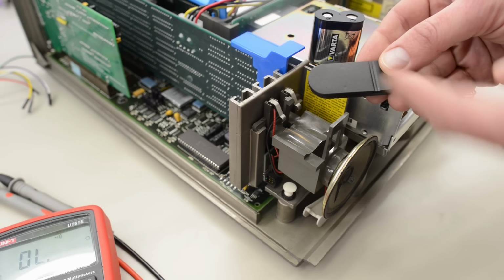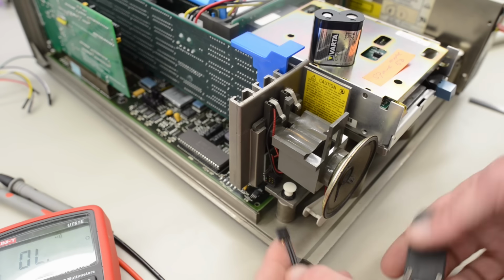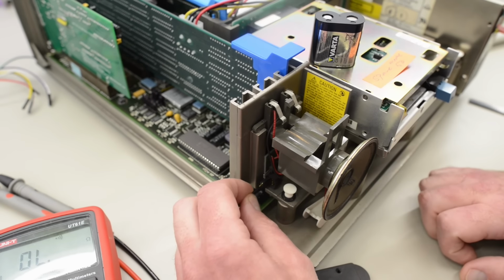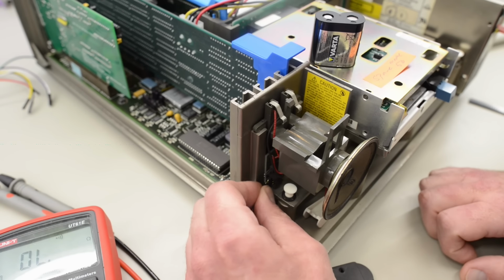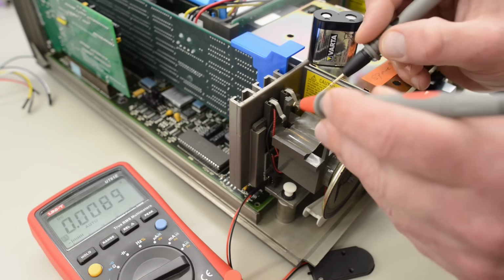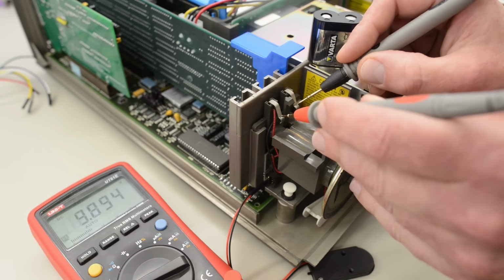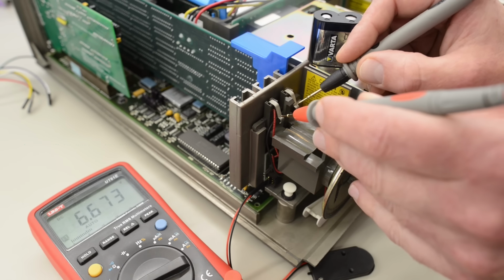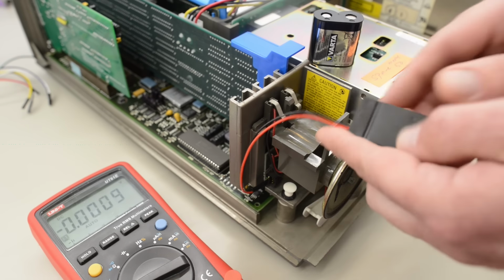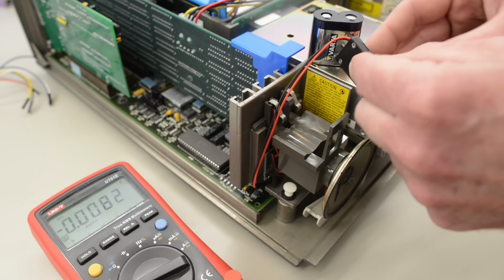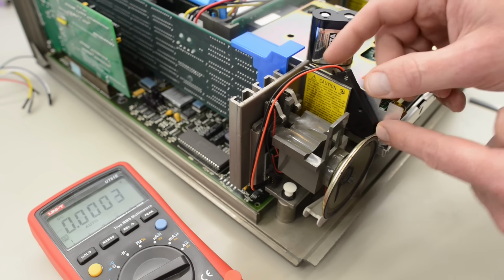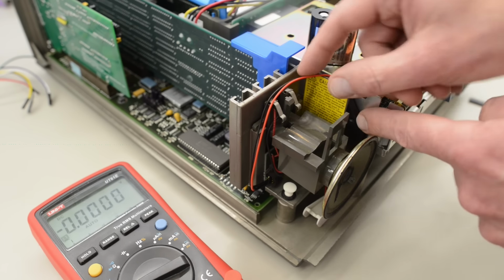They are connected in series, so we're getting about 6 volts. And if we connect it to this connector down here, we should now have 6 volts here. We do, 6.6. Then I guess we need to store it away here somewhere. Oh, there's actually a perfect slot for it here. Yeah, I think that's a better solution than these bulky old batteries. Let's give this a try.